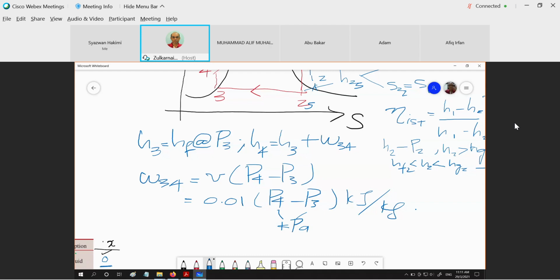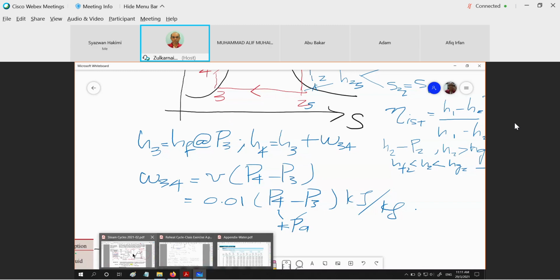Right. So this is what we have looked at, the usage of superheated vapor entering the turbine. Why do we need superheated vapor entering the turbine? Because we want to increase the work output of the cycle. Then next, like Tiva said yesterday, we also can have an increase in work when we increase the pressure. Now we try to analyze whether it's true or not.